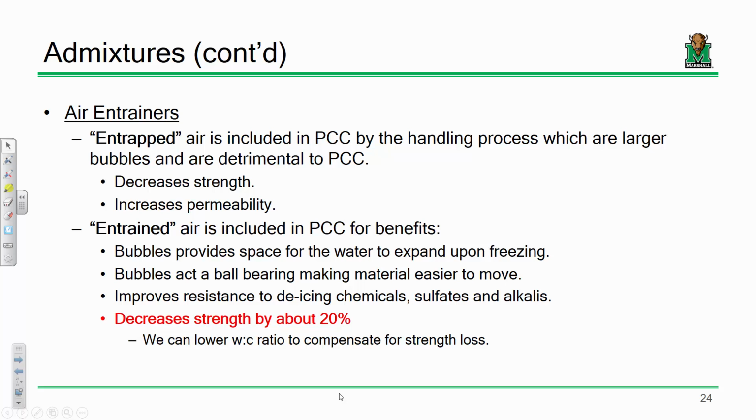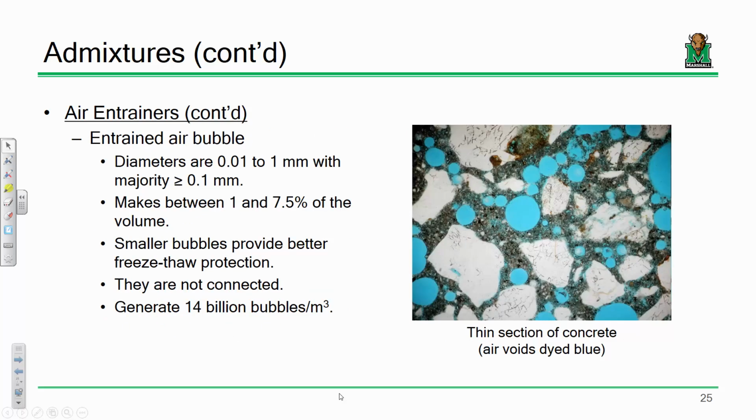So throughout the year, a given exterior application of concrete is going to see one heck of a thermal shift, right? Now, you folks who had me for deformables, even if you didn't, I think you'd recognize this. When things heat up, they tend to expand, and when things cool down, they tend to contract. That's just physics, okay? So having some controlled amount of entrained air in a given concrete application is actually a good thing. It can provide a little bit of a buffer for that internal freeze-thaw expansion, and can control that behavior and even prevent cracking a little bit.